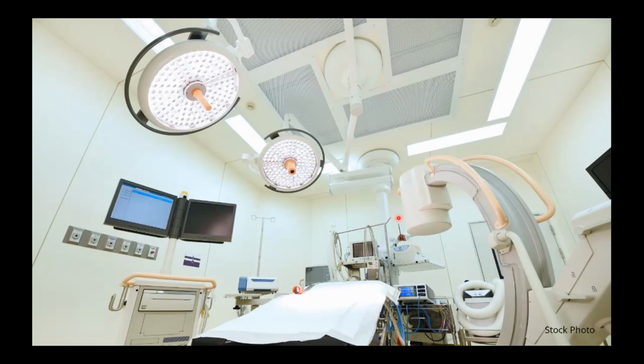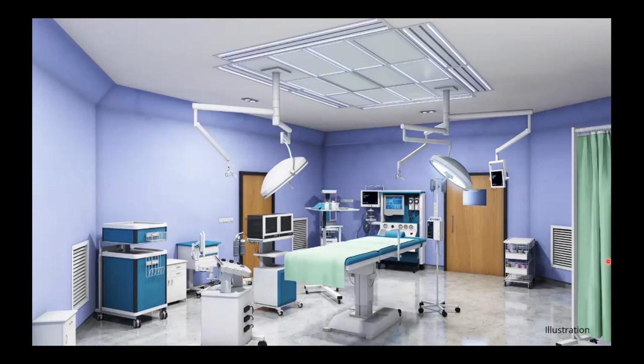And finally, we finish off with a perfect layout, which of course includes all the Krueger 5000 laminar diffusers, the sterile flow, and the Krueger Frameworks heavy-duty sealing grid. And we have our return grills mounted 8 inches above the floor in multiple locations. We have actually 4, but the 4th wall is hidden in this view. And we have our laminar diffuser array providing adequate coverage over the table. We've integrated the lights directly into the laminars, so we have full laminar coverage except for the 2 blank-off panels that must be located for the penetration of the surgical booms.